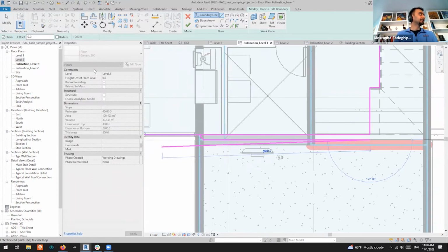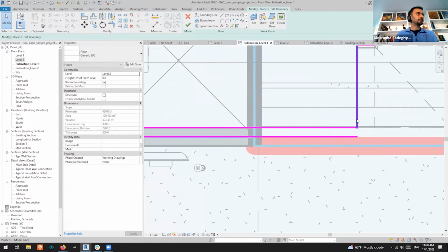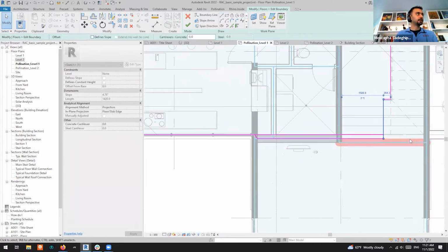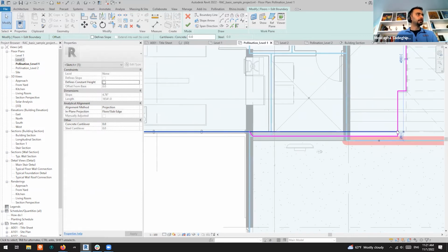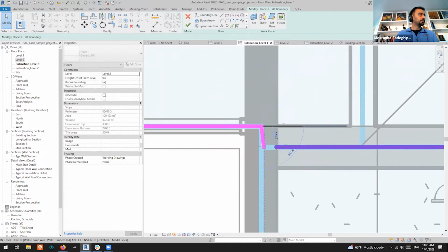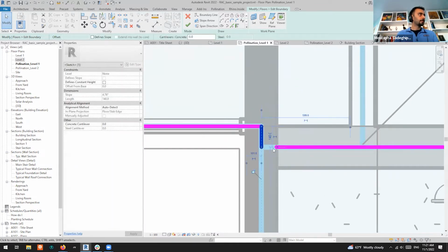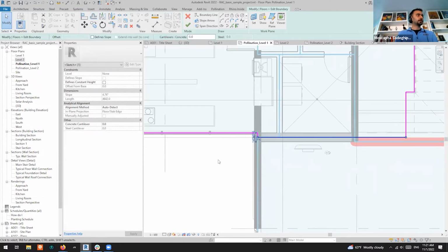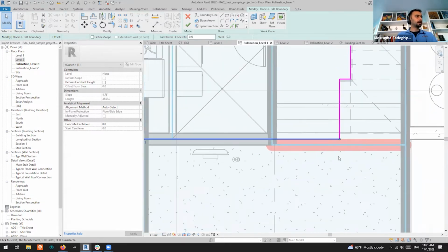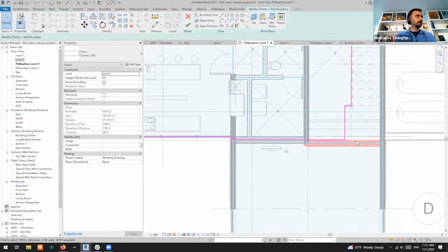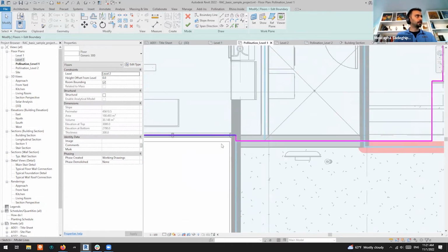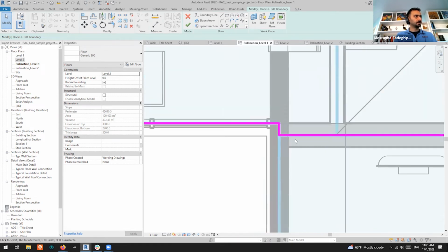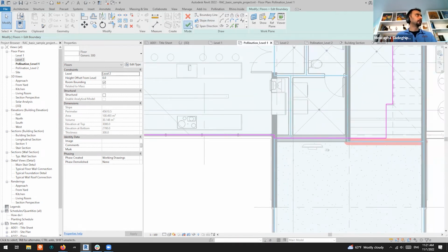Okay, so I did this. Click on this. I'll move this one here. I know Revit has trim and things that should allow you to do this better, but bear with me. So I cleaned up this. Then the next thing I want to do is to align this one, which I can't do right now, so I have to go out and then align this. But this is all I did. Basically, I moved that line here so it meets the room boundary. So I say, okay.